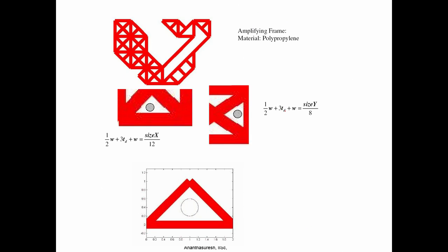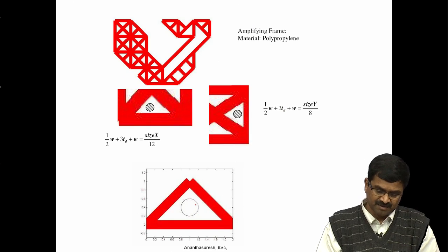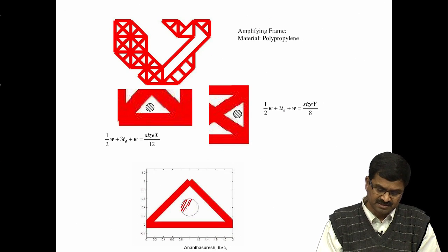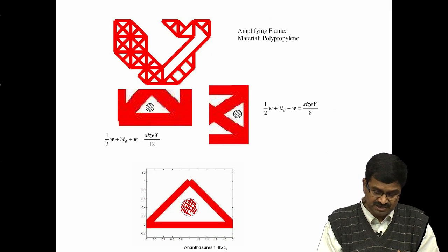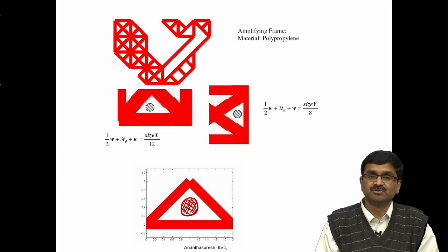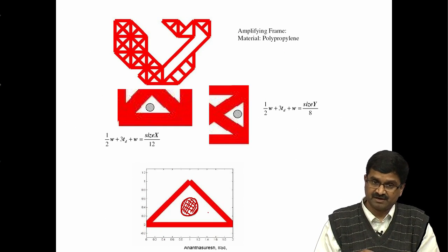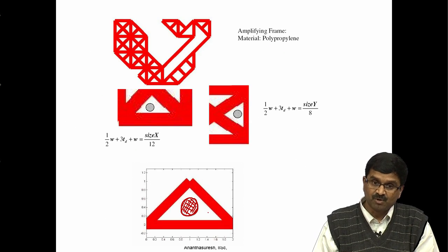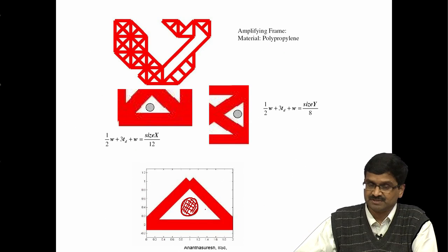In this case this illustrates how the in plane width can be changed within that mill diameter. This is the mill bit, and based on that we do not want to increase the width to more than a certain value, because in that case it will not be possible with this mill. If you make it really narrow, it takes care of that. How large you can make it, how small you can make it, is based on the manufacturing process specifications.